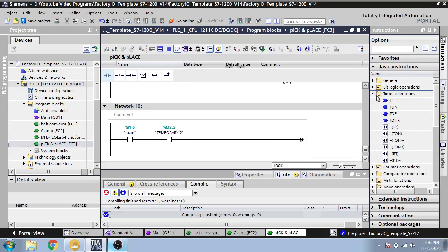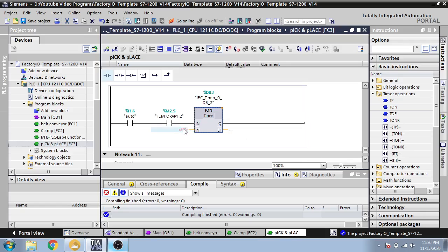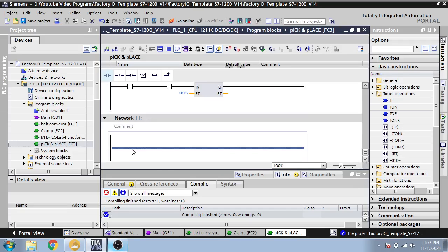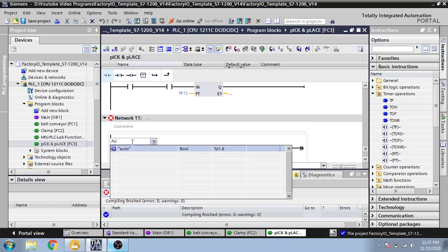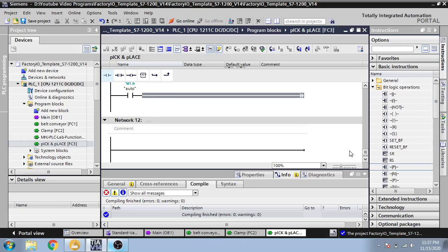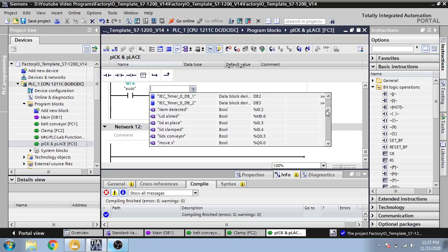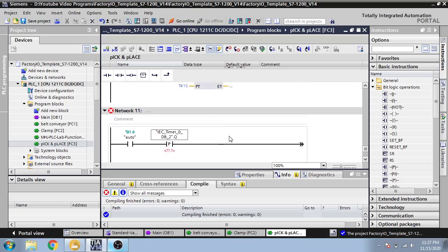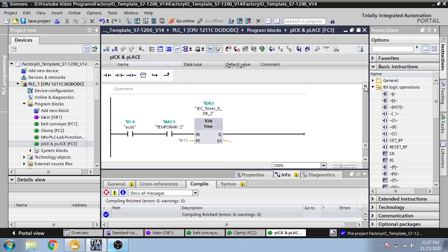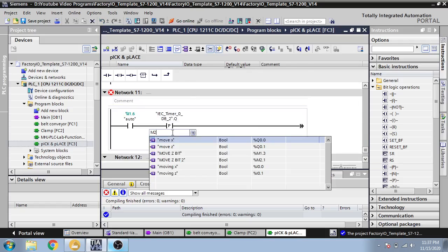We need another timer there. Another T1, which we call the DB2. Again 1 second. I am just using an auto. And again, which thing do I need? We need a positive edge. We need our DB2 here, and also 2 as an output. So what memory bit did we last use? Which is 2.5. Now I am using M2.6 there.